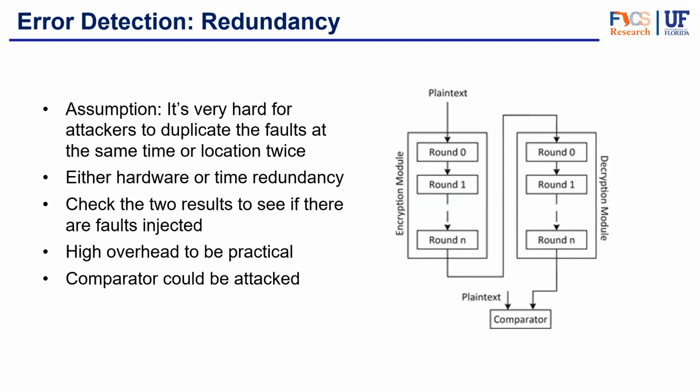One famous technique is the voting mechanism, or triple modular redundancy (TMR), where a voting system determines which part of the design has the fault and recovers from it. Another technique is repeating the same operation at different times and comparing the results, so we can recover from temporal attacks.